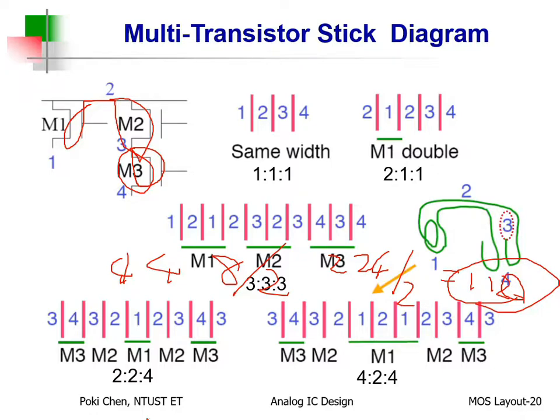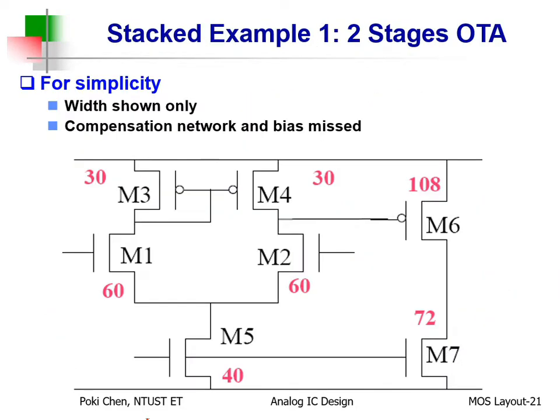Very simple. So you can make it for the third order, for the fourth order, but anyway, my recommendation stops here because even for the best IC design house in Taiwan, they only require second order common centroid layout. So I think my 3 recommendations will be good enough for you to not only survive in the future, but live happily ever after. Okay?